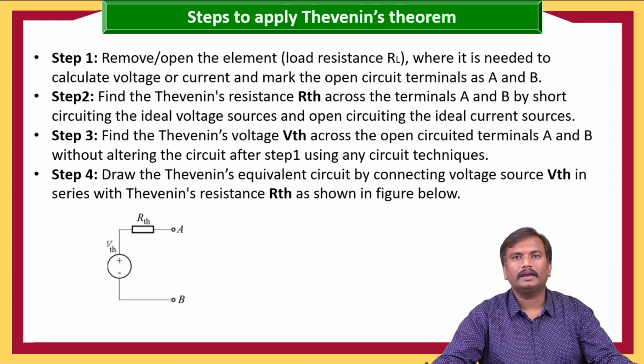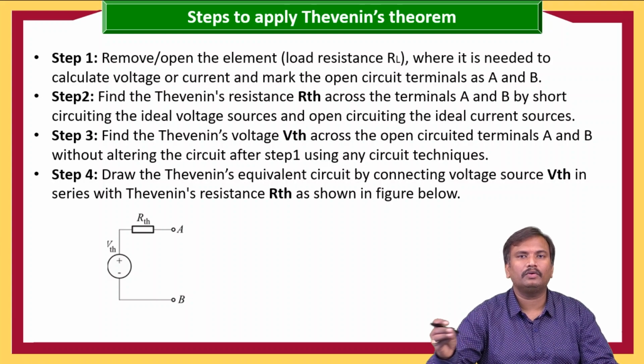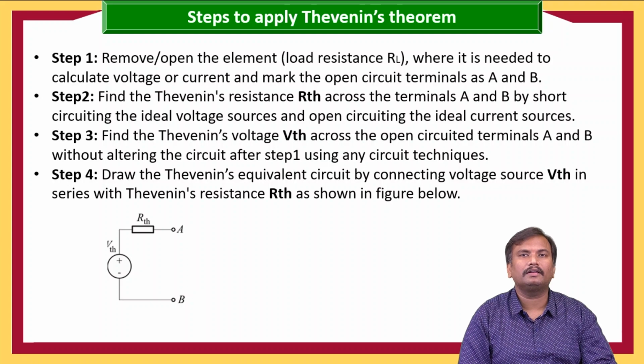And then after, in step 3, we are going to calculate the Thevenin voltage across the open circuited terminals without changing any other terminal, only whatever the load resistance which we have removed between those two terminals, we need to calculate the open circuit voltage, that is known as Thevenin voltage.